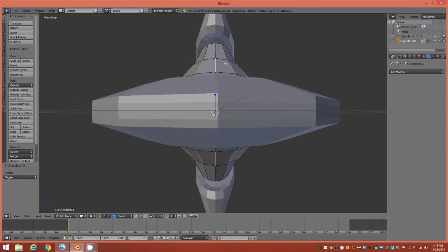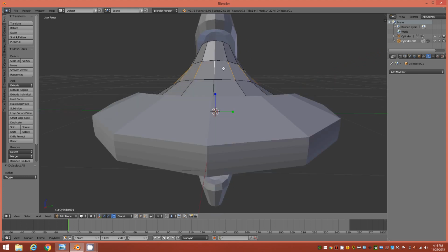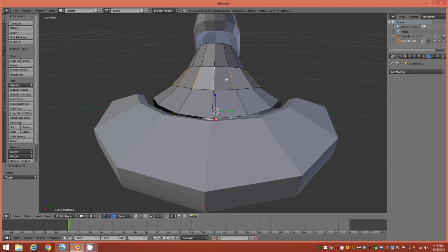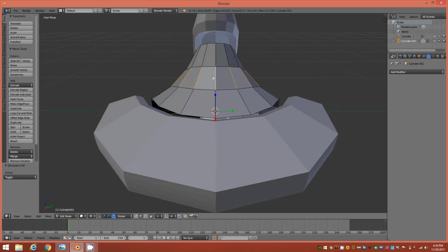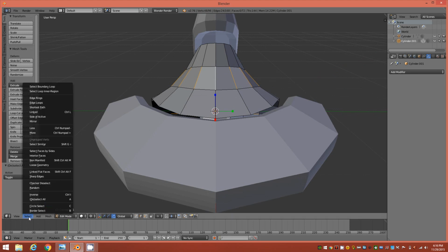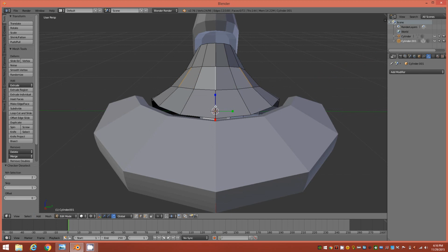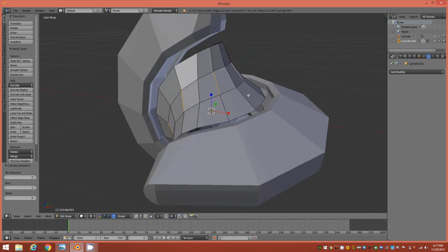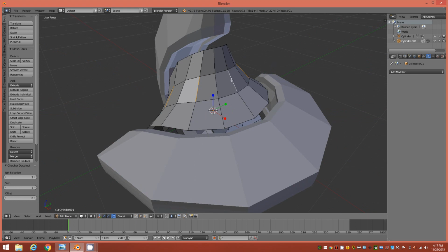So this is the right side view, and now that we have all of these selected, we're going to look at it from head on, and go down to our select panel and choose the checker deselect. On this one we want to make sure that the center edge is selected. When we initiate our checker deselect, we're going to stick with the defaults here because this is exactly the selection pattern that I want. Every other edge starting with this center edge.